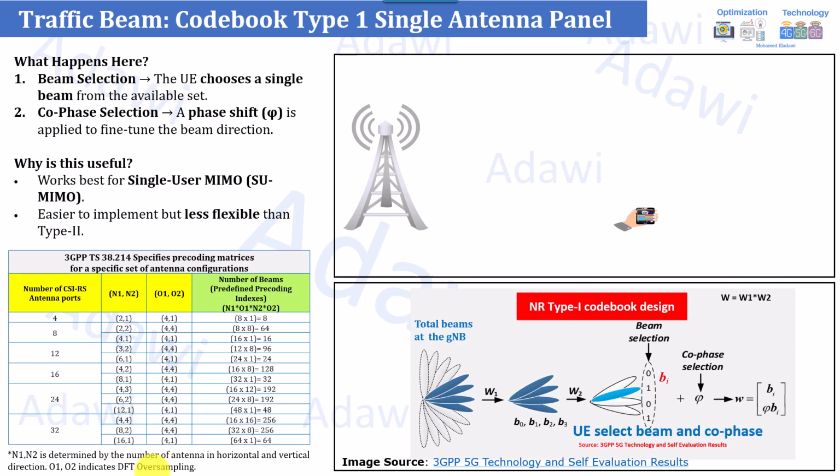For example, in this scenario, you have 16 multiplied by 4, so you have 64 beams. This means you will have more, narrower beams. This means you can achieve a much better signal to noise ratio, or maximize your signal to noise ratio for the users. So this will result in a much higher granularity if you selected the 32, for example, scenario and 16 by 1 for the horizontal direction. So this can have a much better performance.